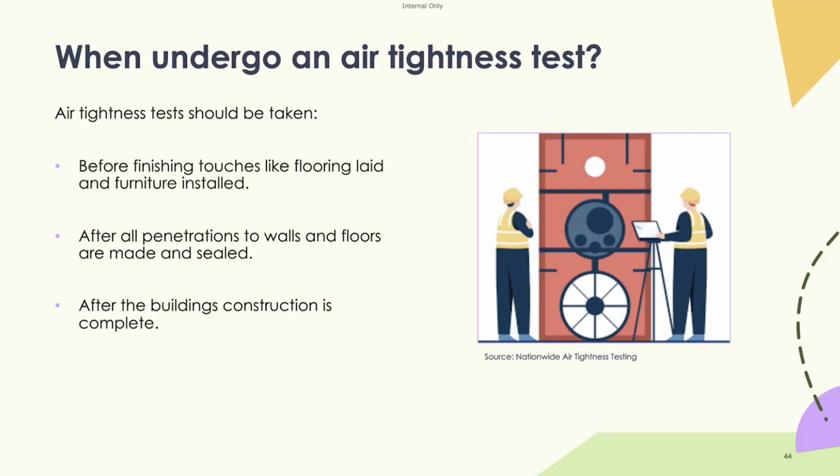And again, if you've put up interior wall insulation and you want to test that insulation line, are there gaps within the construction? Have we taped the insulation appropriately? Ground floor insulation, ground floors, timber suspended floors are usually very, very leaky. If you install those timber battens and put insulation in between, you can make sure that there's no air gaps within that particular construction. It's nice and airtight, and an air membrane that you've probably installed as well has been installed properly. So it's a good opportunity to verify that these products have been installed in line with the requirements. And as I mentioned before, it's a really good opportunity after the building's been constructed to complete an air test just to verify that the appropriate ventilation is installed.